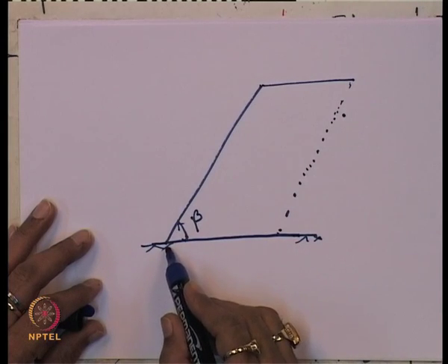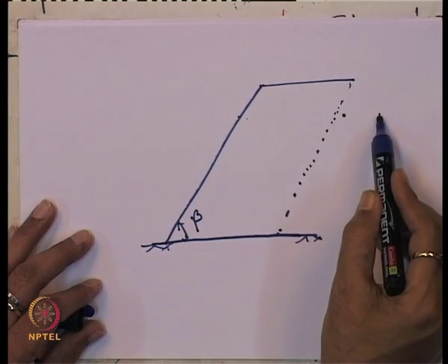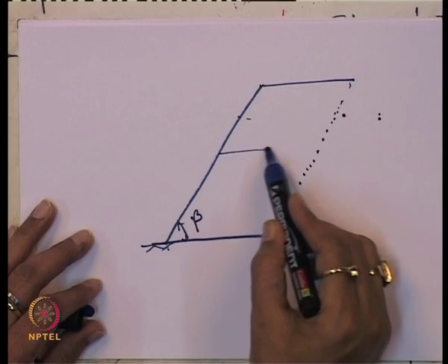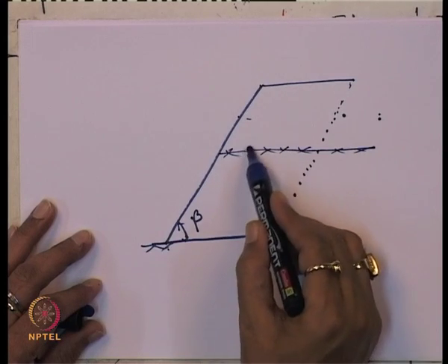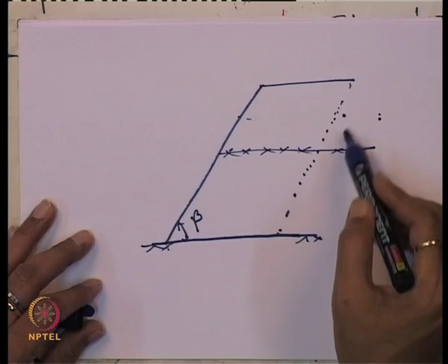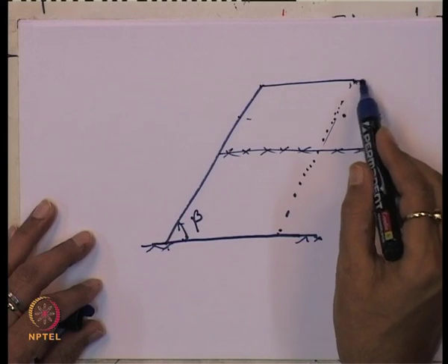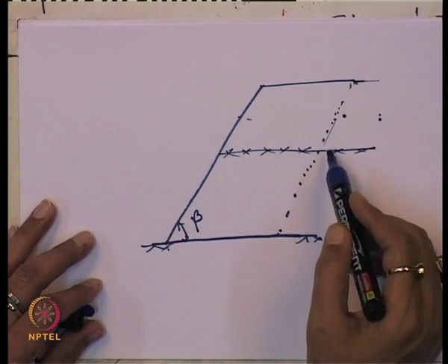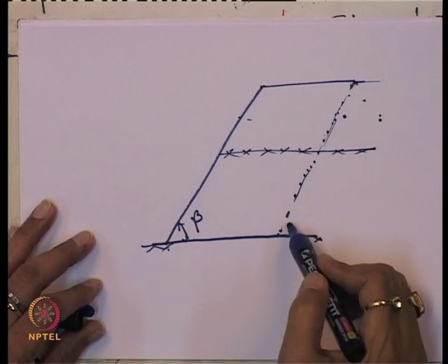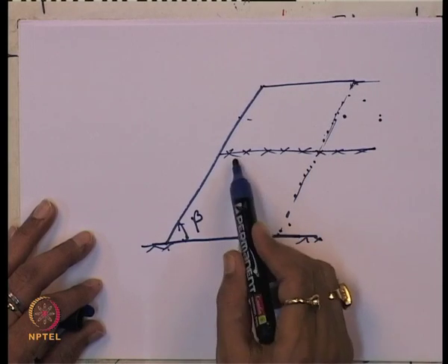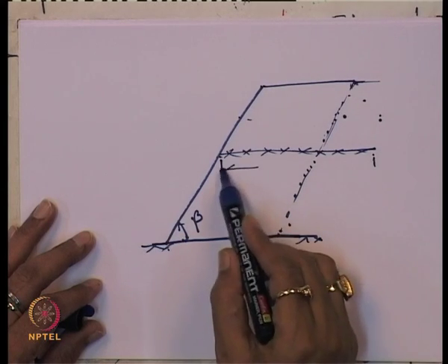Suppose if the length is required more, so you can place one layer of the geogrid material here, and there is no space. You cannot use this space, like let us say any concrete railway or a steep slope, and you cannot go beyond this line. But as per your design, you require the length of the geogrid from here to here.